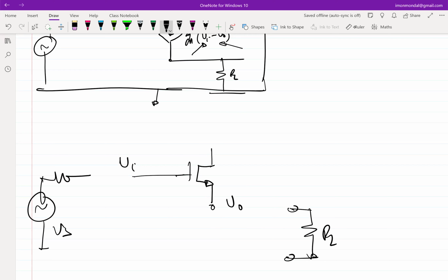So now the question is, if I connect everything simply like a small signal model, it's not going to work, because the transistor has to be set up to accept some quiescent current so that I get the gm and so on. So let's do the biasing first, and then we'll put the incremental part. Then we'll put vs and RL wherever they are supposed to be. At least we know that incrementally vi should come here, and RL should be connected between v0 and ground.